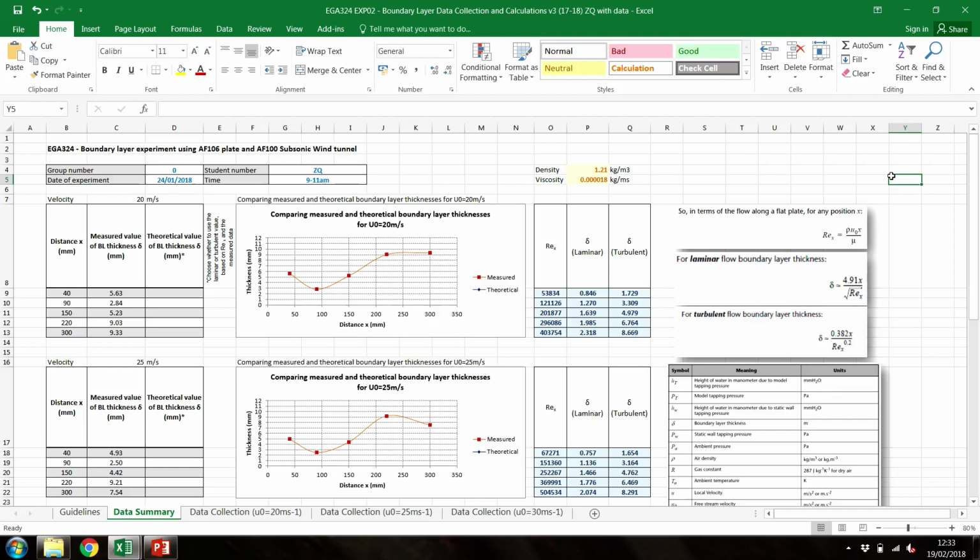Now, if I were to compare that to the theoretical values, what did we say earlier? We said that in the boundary layer, a Reynolds number below about 500,000 is still before the transition point. Our maximum Reynolds number there is 403,000.